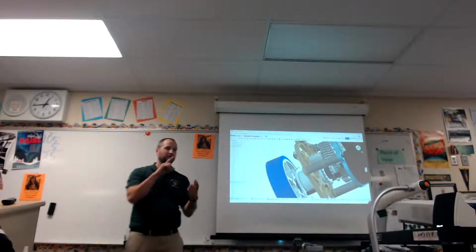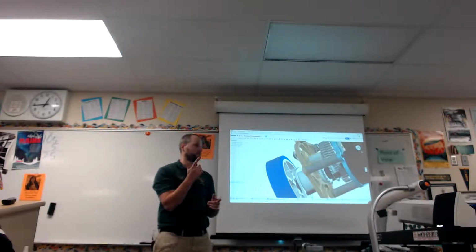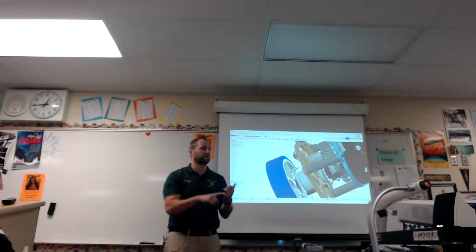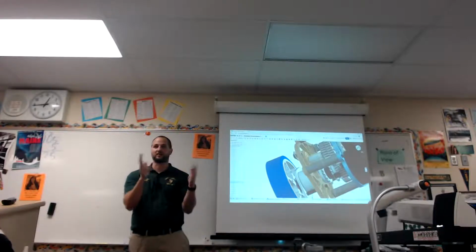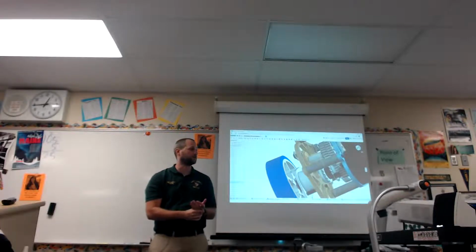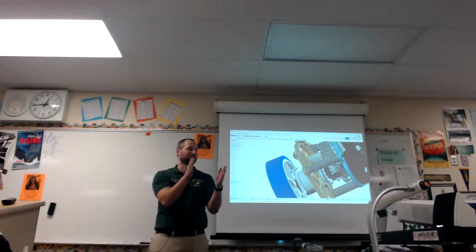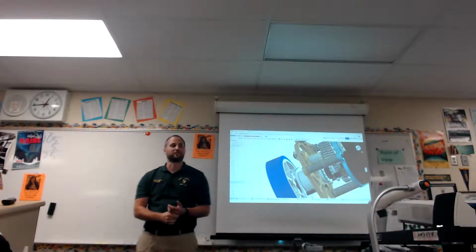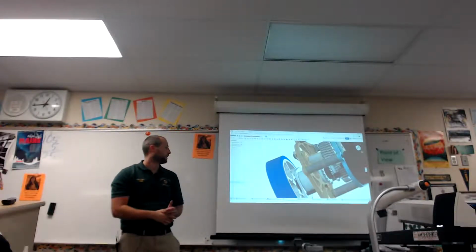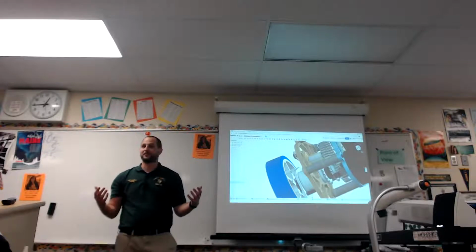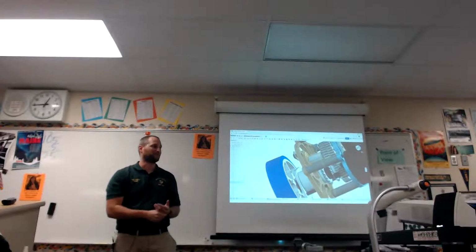So it actually grabs and creates little geometric coordinate systems at those different points. You line up your X, Y, and Z axes. You can set constraints as far as how far they're allowed to move, which is another way you can use to orient them. Just give it a rotation angle that's between negative 200 and 200, and it will rotate around to 200 degrees. So you can get things done with a single mate connector. It's really helpful because when you go through and you make changes, things don't break on you.